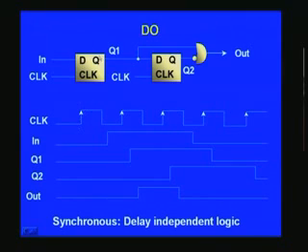And first flip-flop output is Q1, and naturally when the rising edge clock is encountered here at this point of time, in is 0. So naturally the output is 0 here, and when it is subsequently 1 here, this will be registered only at the positive edge of the clock. It should have happened here, but owing to the delay between the clock and the Q output, this is naturally staggered a bit here. It is delayed a bit, and otherwise this is nothing other than the input itself.